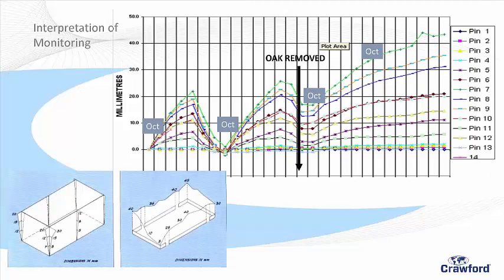So this is October, and if you didn't know, although damage might be discovered in August, in July, and September, damage is usually at its worst in October. After October, you will start seeing a reversal of fortunes. So you need to sort of hang fire till then. And here's the proof. The levelling, the property was at its lowest point in October, and then it started to recover. We said it's an oak tree.